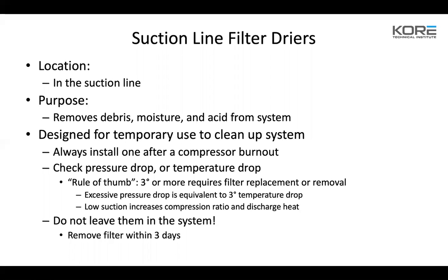So I have had a couple situations where some have gotten missed, and we found that the restriction was at the suction filter. So again, just verify that those have been pulled. If you ever have a major burnout system on a rack, or you're doing a big change out on a system, you want to throw those back in temporarily for a few weeks, let it clean up the system, and then make a scheduled appointment and go back and pull those out.